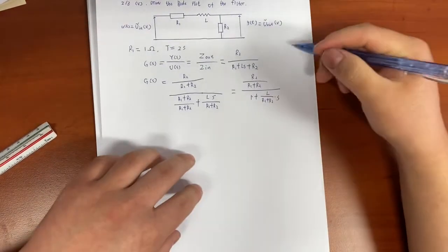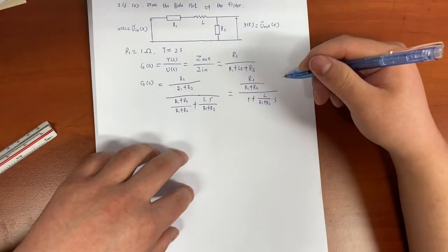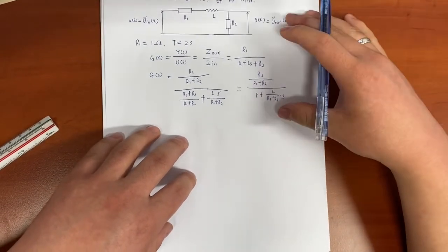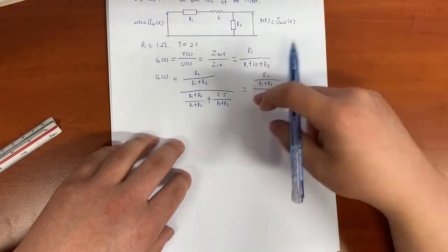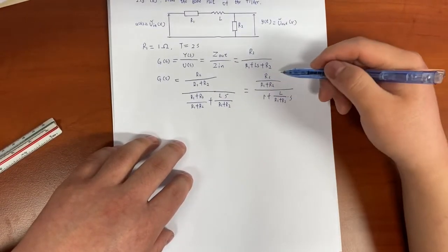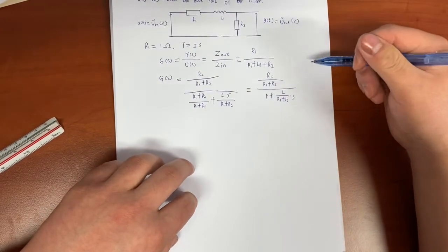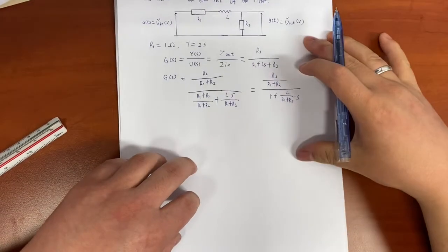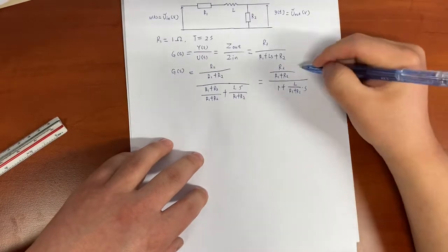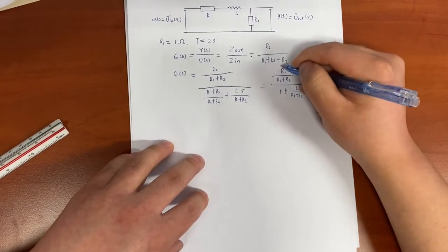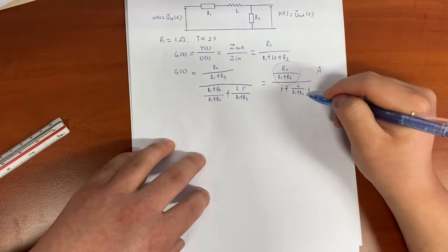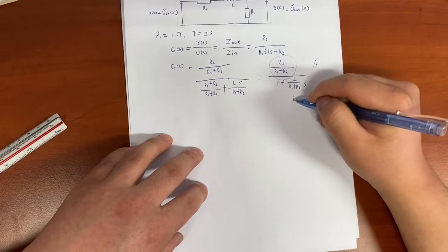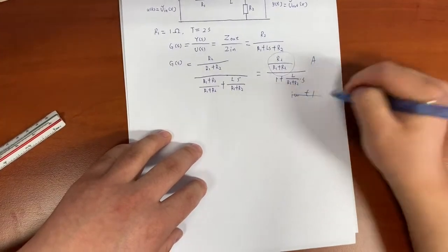So why we do this method is because we want to get this basic transfer function, so we can calculate the parameters. And if you look at this transfer function again, it's like a one time constant proportional type function, because this part is A, and this is like j omega, a constant T, plus 1.